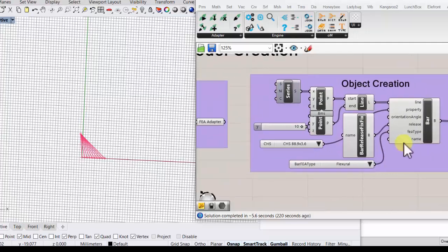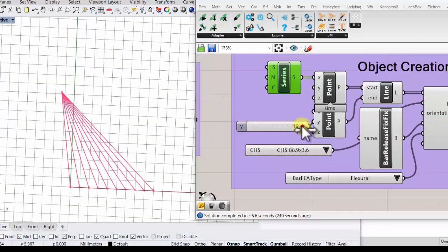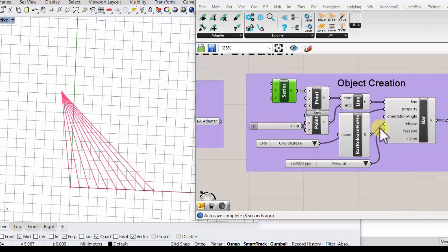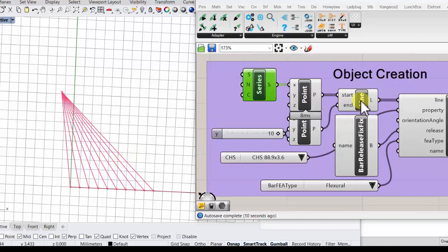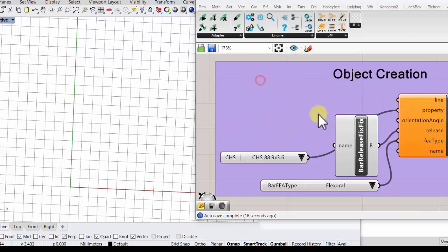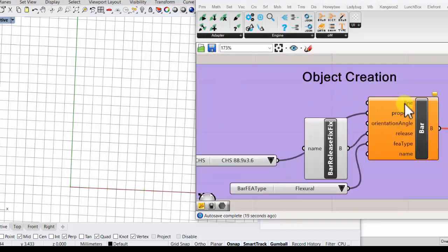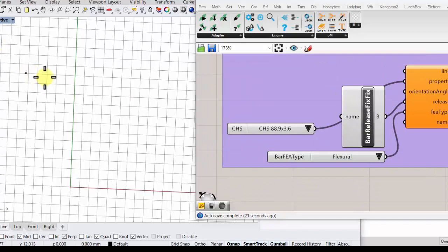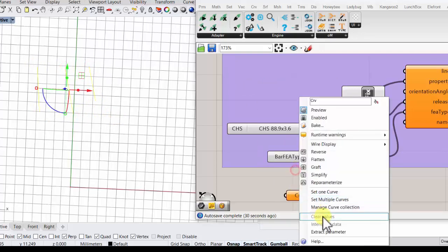Now, the deal is most of the time, we've got to get over this idea that we're going to be parametric designers and every single bar is going to be set out parametrically. We know that most times the column center line is dictated to us, and we're going to have to feed that in some other way. So potentially this part of the script goes away, but either way, we're going to need to feed in lines, right? So I could just as easily have done something like this, where I create a whole bunch of lines out here in space, reference them into Grasshopper,